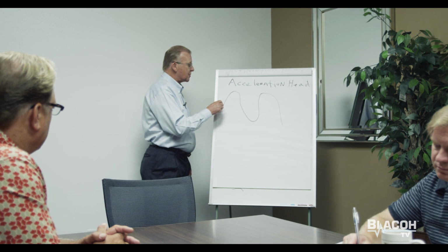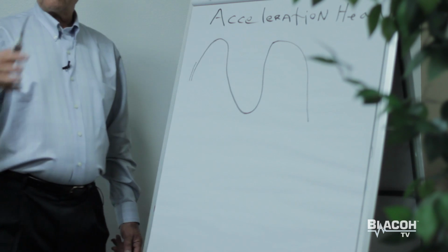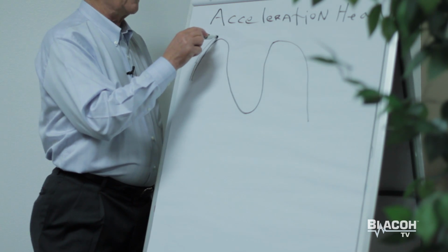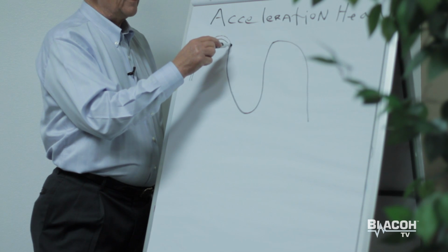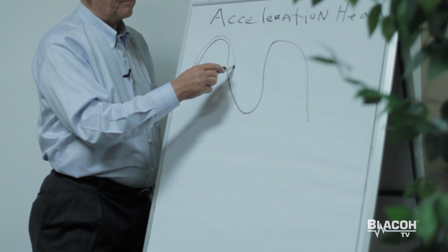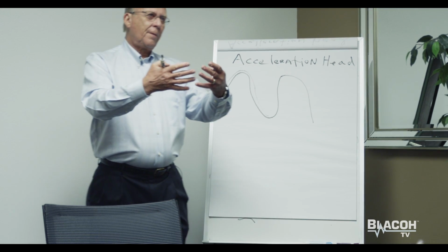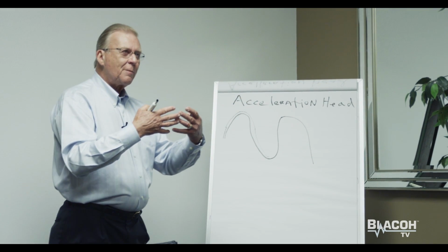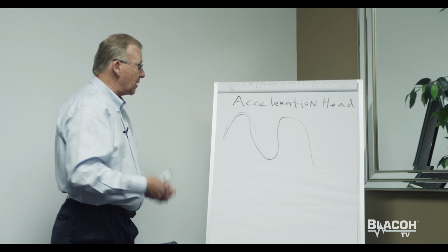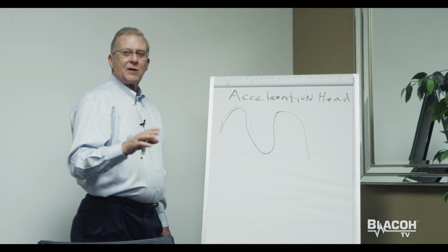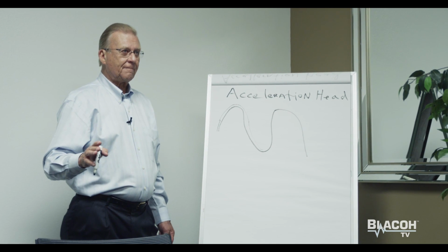But the flow starts and builds or accelerates, if you will, through the stroke until it reaches midpoint. And then the flow starts slowing down till you reach the point where the piston and the diaphragm pulls back and recharges on the inlet stroke. And the flow, depending upon the type of pump, can actually stop momentarily.